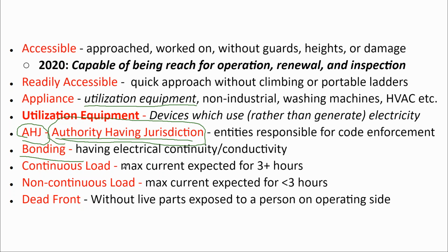And so you have a return path for that electricity to go into the load and then out of the load. And how that return path is bonded to ground creates the flow of electrons. But we don't want that flow of electrons to occur anywhere in the household, such as it would during a fault. And so we see the term bonding to denote when we're connecting two pieces of metal together, and then eventually that might be connected to ground, or it might already be part of the ground, but it's not as specific as the word ground is.